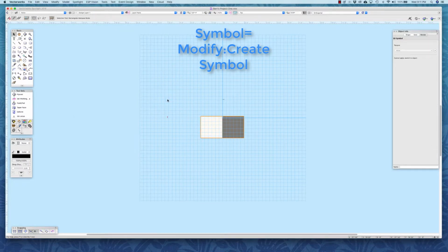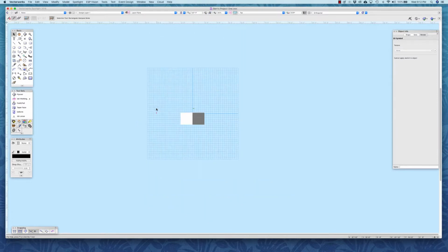In 3D modeling, best practice is to create symbols anytime you know you'll be using multiple copies of an object. Multiple copies of symbols are more efficient than multiple copies of individual objects, and symbols greatly simplify making changes that may be needed later. We're going to be making about 150 copies of these cubes, and if we decide to change the color later, for instance, it's much easier to just change the one symbol than the 150 individual sets of cubes.